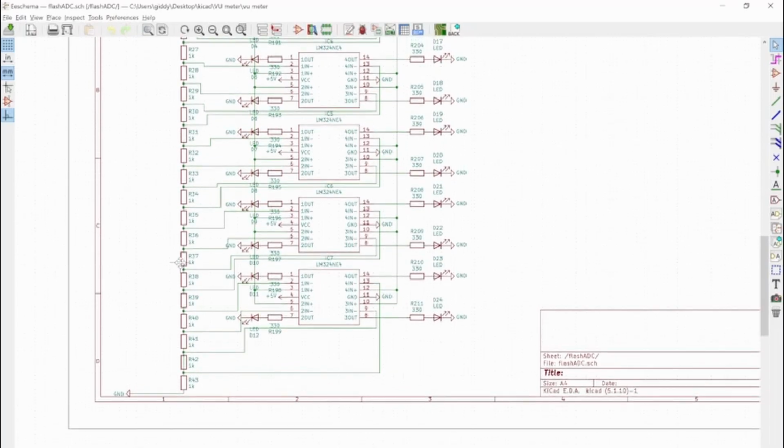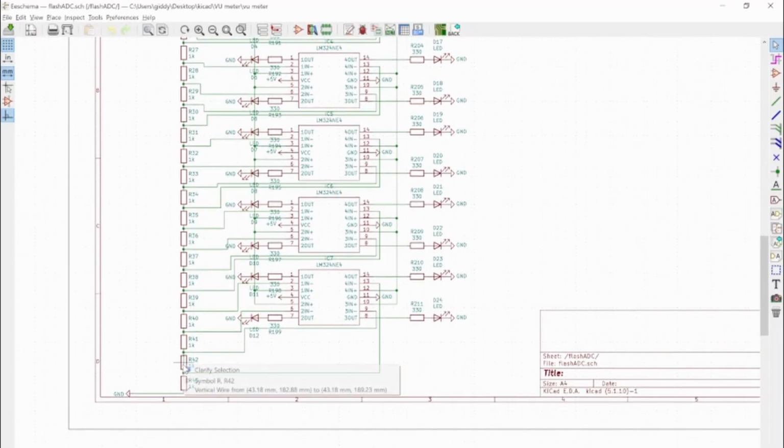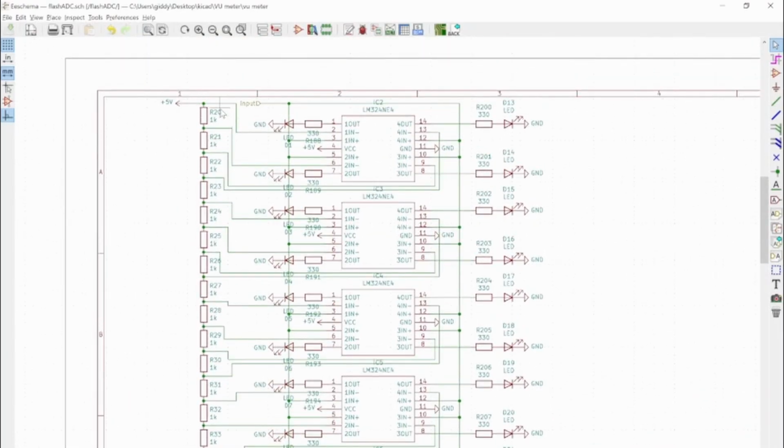So what I've done to fix that is, why is there a wire there? Let's just delete that. That shouldn't have been there. Oh, right. So what I've done is basically just replace this 1k resistor with a 680k resistor, and that has basically put a huge voltage drop across this resistor, so that this is now basically 1 volt, and everything below is millivolts apart, which means that much more of the signal will actually go to the top of the meter thing, LEDs.